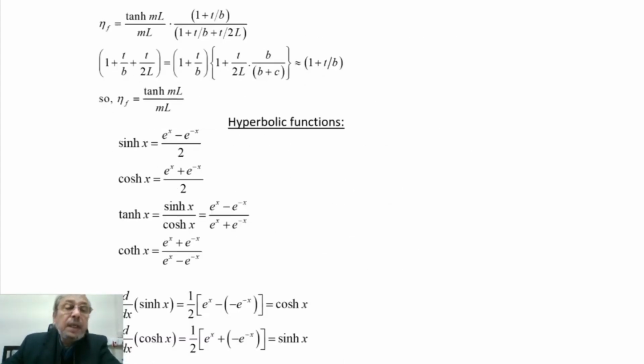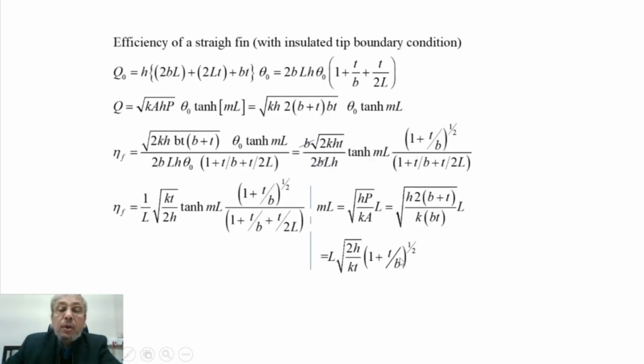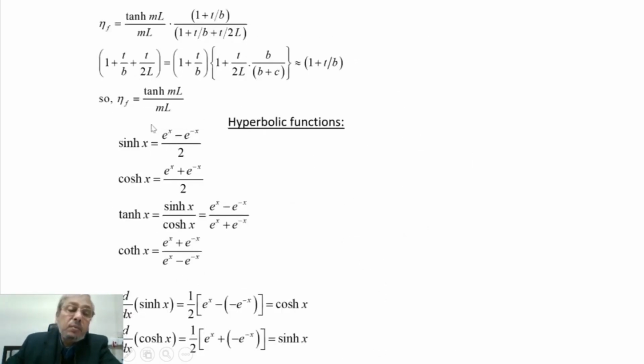And also we have just discussed how fin efficiency can be defined, that is heat transfer rate from the fin surface, actual heat transfer rate divided by heat transfer rate which would occur if the entire fin surface was at the base temperature T0. So we got that.